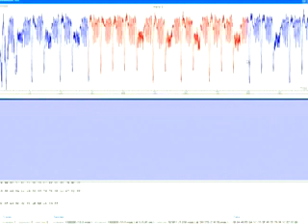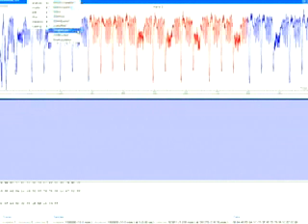So a simple countermeasure against this SPA, and I do want to say this is not the best countermeasure, is to do a so-called bit group-wise implementation. If you do a little mathematics, you can make it clear that you can pre-compute a couple of multipliers, and then what you do is a square multiply with a pre-computed multiplier, but then for every bit group.